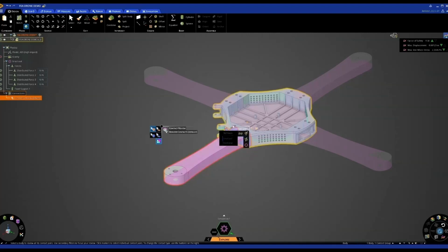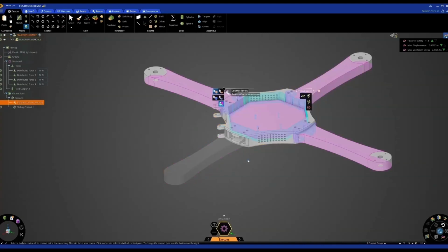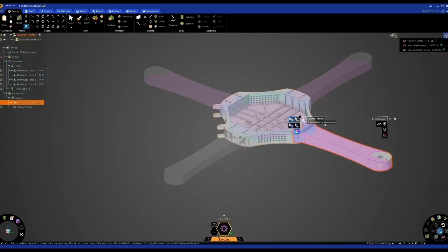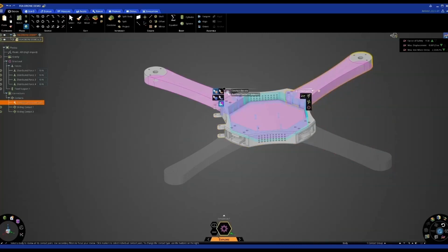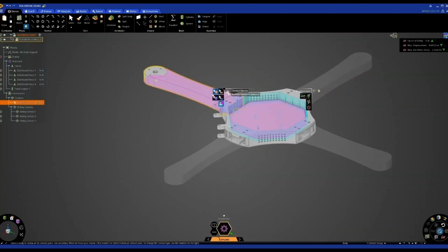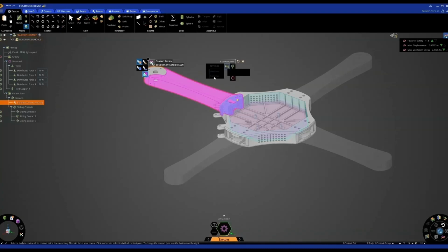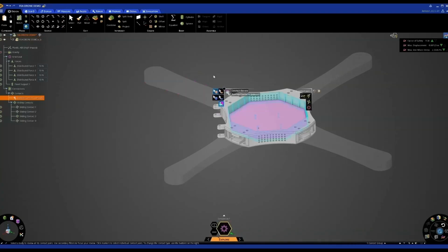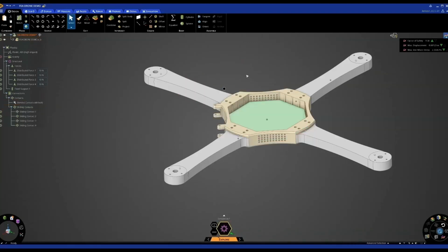Because it looks like obviously we've got some bolt holes that maybe will hold this part together, I'm just going to convert those to sliding. We'll do all the same to these, and we can go through them very quickly and just convert these to sliding. You can also see that we can use idealized or frictional, but I'm going to just use idealized for the time being. So now we can see that of the bonded contacts, I'm just left with this sort of plate on here, which I'm okay with.